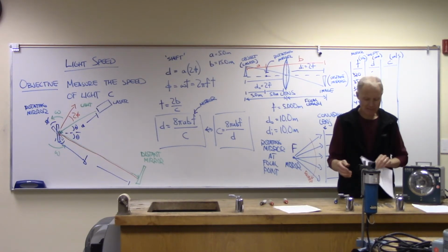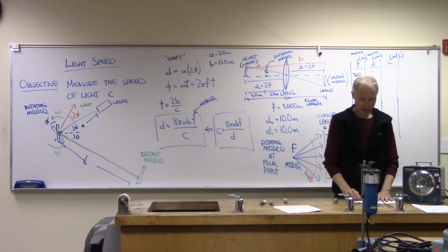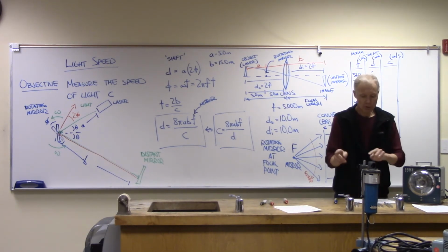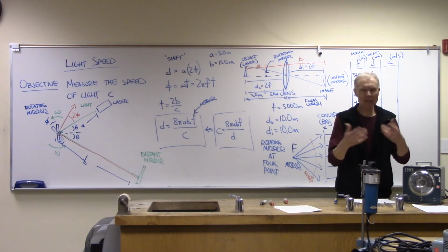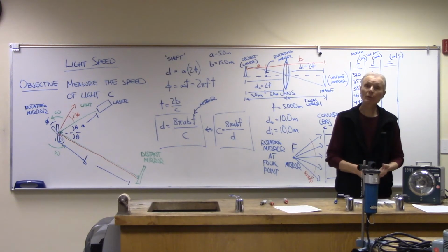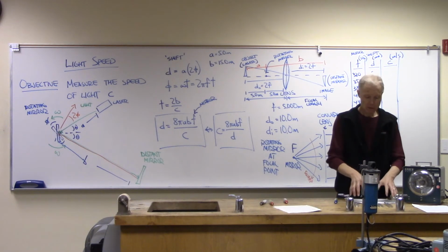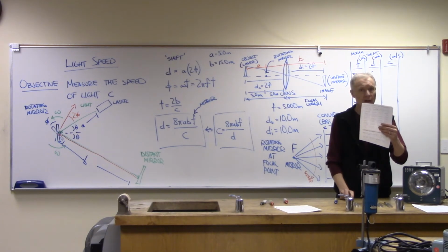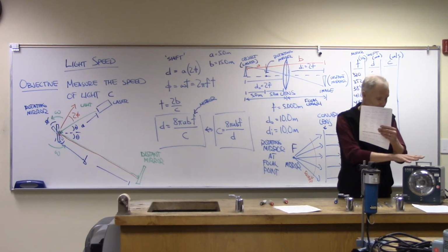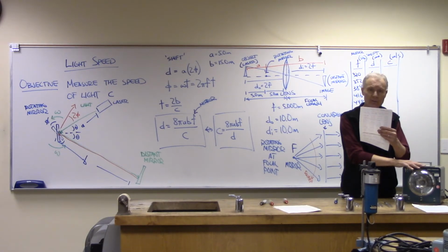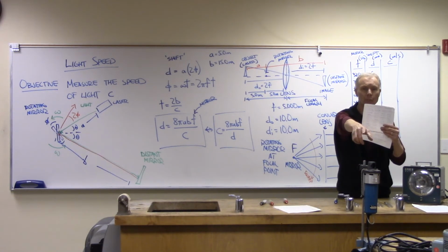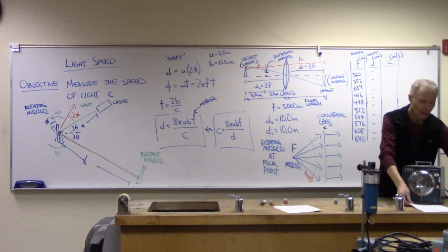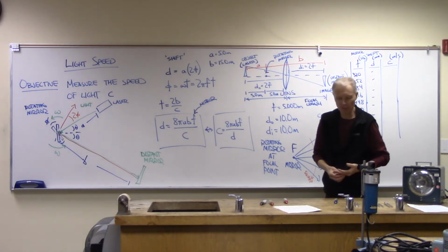At that point, I was feeling pretty good. Everything seemed to be pretty consistent. I cross-checked all the frequencies because these frequencies are in a ratio of 4 to 5 to 6 to 8. You guys may have seen that in Physics 4A, looking at harmonics. So these are all harmonics of each other. And so there were certain frequencies that I was able to confirm using the strobe light, and then use that confirmed frequency to calibrate the motor. Everything seemed to hang together pretty well. Of course, there are little limitations to what we've done here.